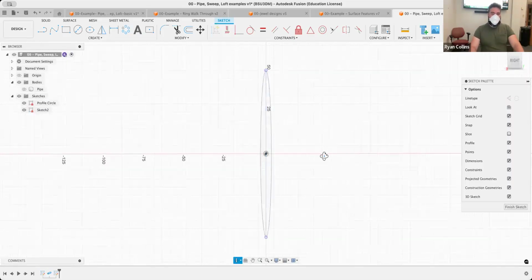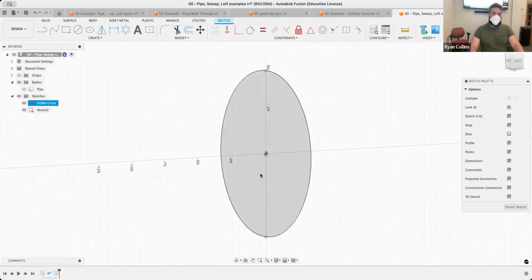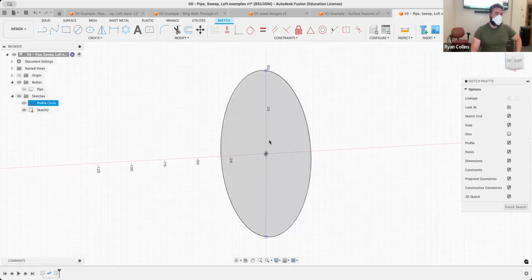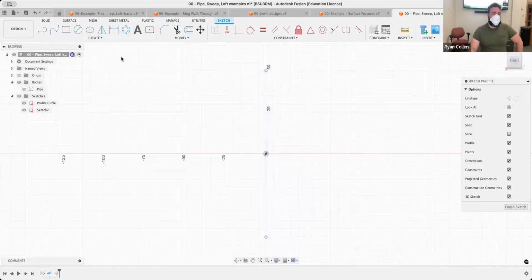So now when I orbit over, you see how it's drawn this line? That is simply showing from the side what a circle looks like. And like what we did from the technical drawings, drafting, what does a cylinder look like from the side? A rectangle. What does a sphere look like from the side? Just a flat circle. So in this case, a flat circle from the side would be a straight line. That's it. So since I'm working here, now I can create my profile.